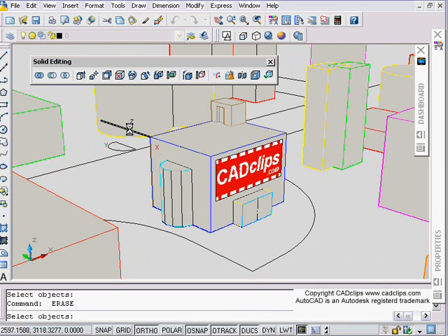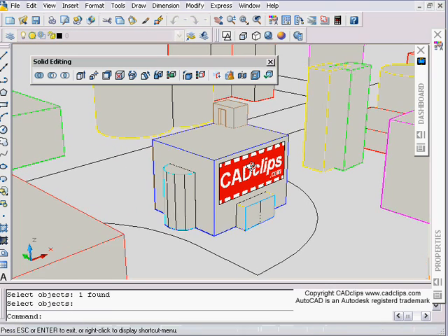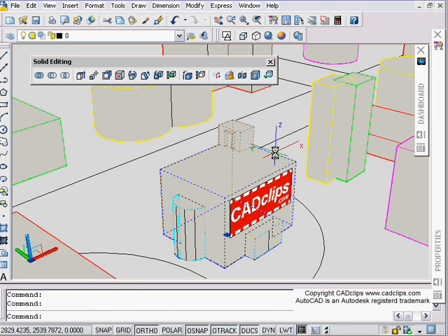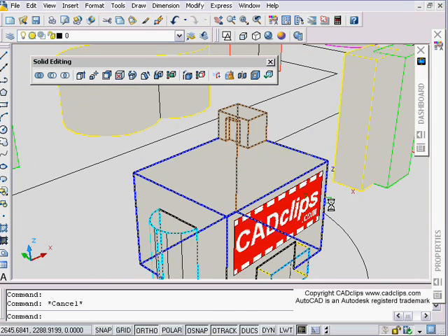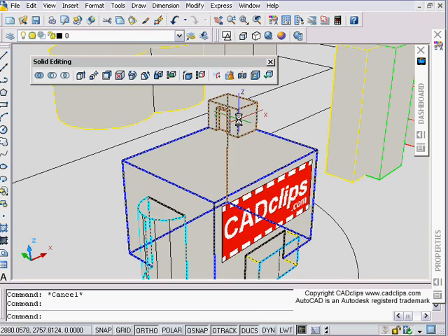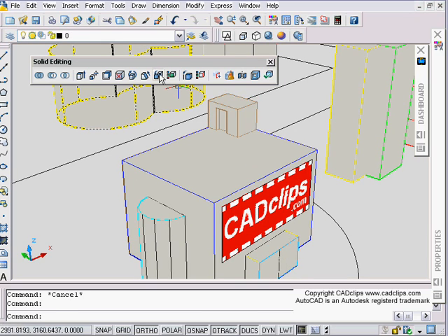So that's one aspect. Okay, now let's maybe look at the top, over here, the top surface. I'm going to use a shift middle mouse button. Now, to get that edging, I'm going to have to make sure that that little penthouse and the top of this building are in fact union. So I'll get that line that goes around.